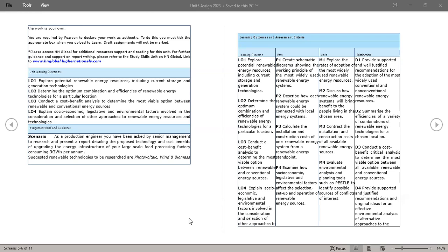For M1, the adoption of renewable, it's likely to be dictated by political and economic drivers such as Net Zero 2050, which is a legal requirement in the UK. Just reiterating, differentiating load factor from efficiency, power and energy. Load factor of PV typically in the UK would be 10%. Load factor in Spain is likely to be double that, simply because they get more hours of sunshine throughout the year. Now, load factor will impact the levelized cost of energy and capex in terms of the payback time.